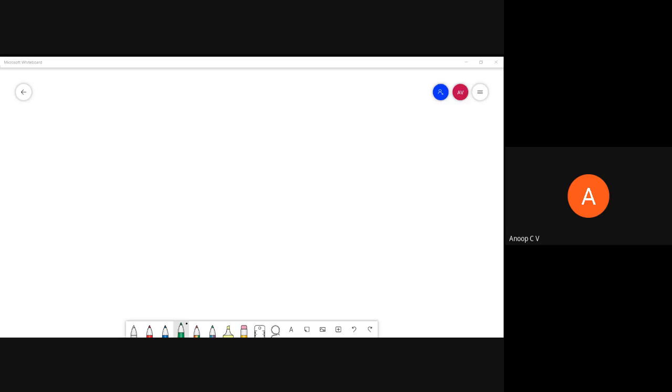Yeah. So good morning and welcome to yet another online tutorial on principles of communication system. So in last session we were discussing about noise. So we have studied in particular about shot noise, thermal noise, and white noise. Right. What we did is we mathematically model different types of noise. Shot noise we modeled considering a photodetector, right? So depending upon a randomly impinging quantum of light, how a photodetector emits electrons and how it constitutes a current, right? And because of that random discrete nature of current, we have seen there will be shot noise, right?